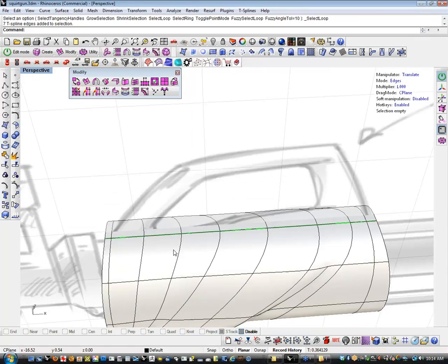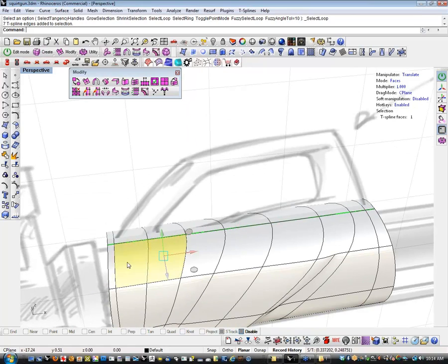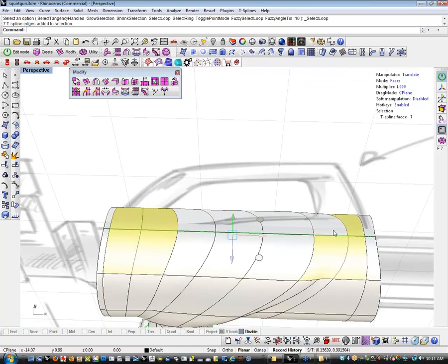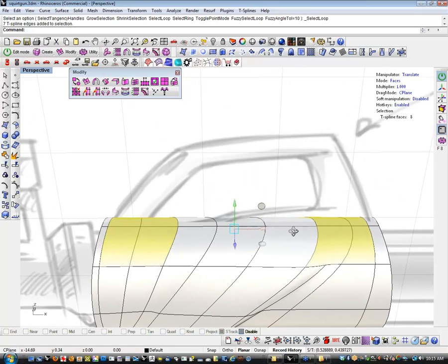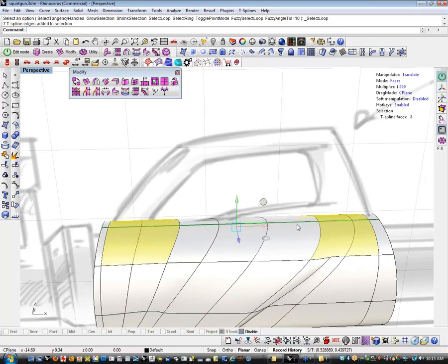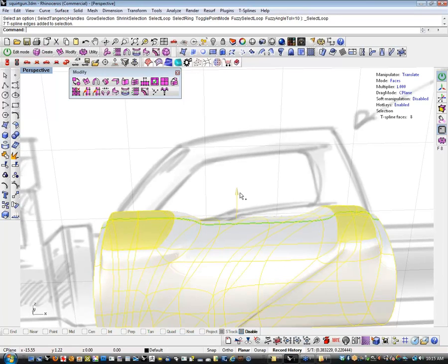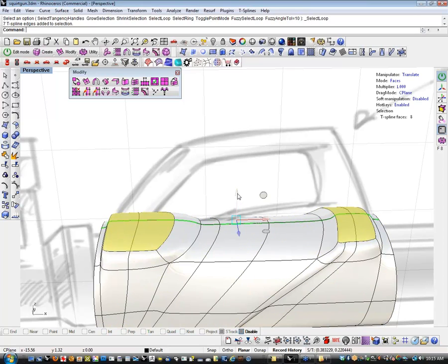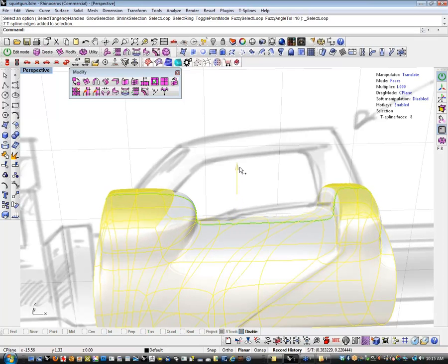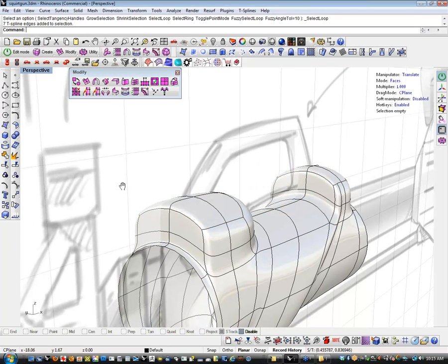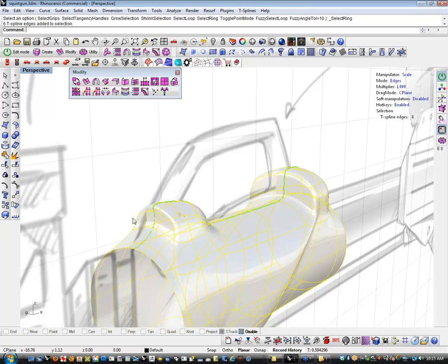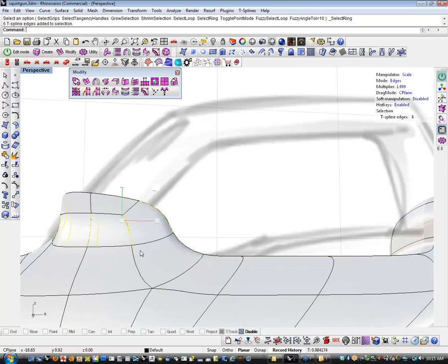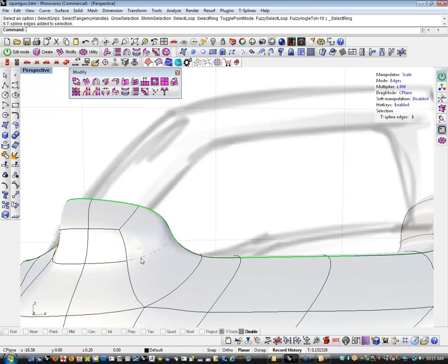So I'm going to pick, and these faces are kind of big for this handle, but I think what I'm going to do is I'm going to just go with that, and I'm going to use that as a fillet, a big fat fillet to go into those things. So I'm just going to scale or alt drag the handle out of here, and then before I get too far into this, I'm going to pick these edges, and I'm going to scale this in way in. And that gives me a really nice transition in there. And I'll do the same with this one.